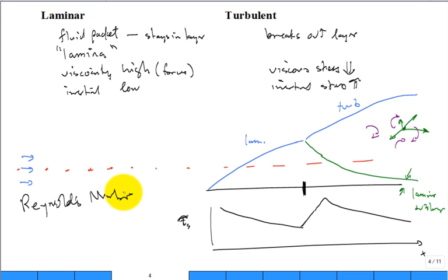Viscous. So the Reynolds number is inertial over viscous. Now, what would be the inertial? That would be something like 1/2 rho u infinity squared, but you could just forget the half because we're just scaling here. So it's proportional to rho, the density, and then u infinity squared.